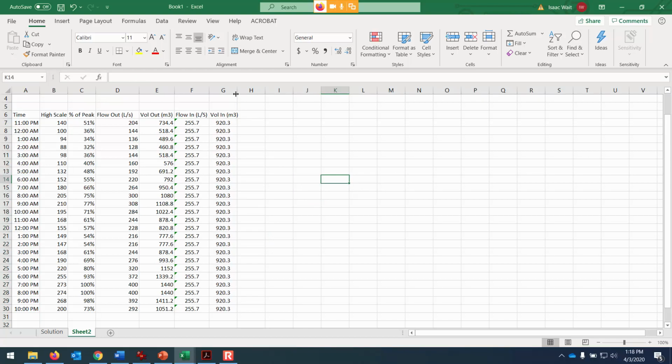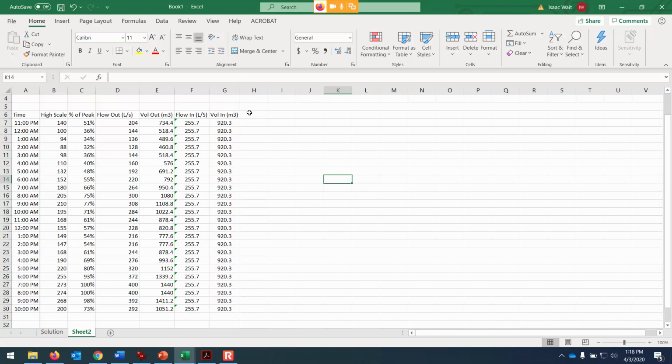All right. So now I'm going to calculate a column that's the difference, dS/dt. So it's the change in storage for that hourly increment. And it's in minus out. So during the 11 o'clock hour, the reservoir fills 185.9 cubic meters. During the 12 o'clock hour, we're adding an additional 401.9 cubic meters to the reservoir.